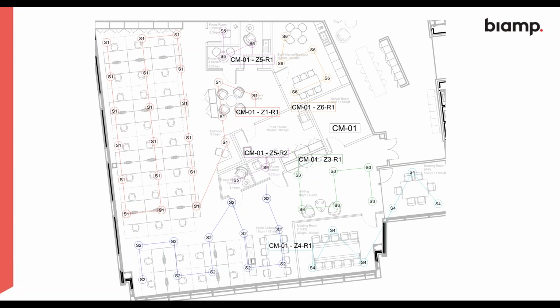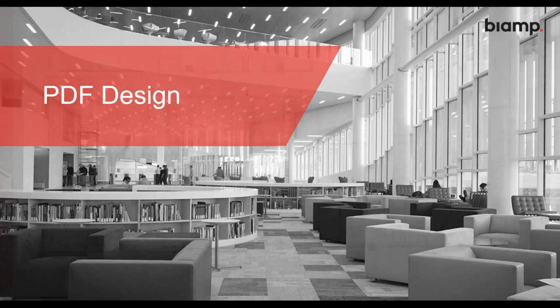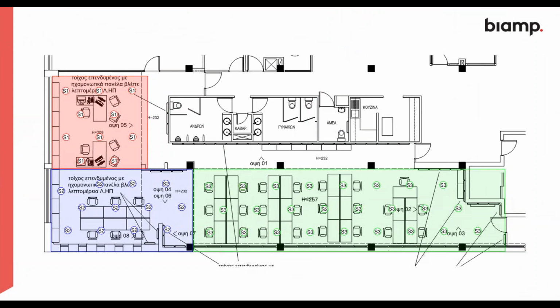You can also use PDF. If we do it on PDF, personally, I use Bluebeam, although any PDF writer can be used. And following a similar format, get a scale off the drawing somehow. In this case, we had to use the door. And we could lay out the emitters like so. Now, what you might notice on here is that the emitters are not following an exact grid. This is because of the size of the space where we had to put 2 in the middle to keep the uniformity.